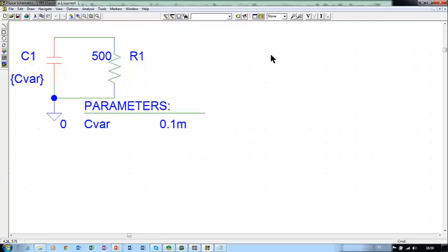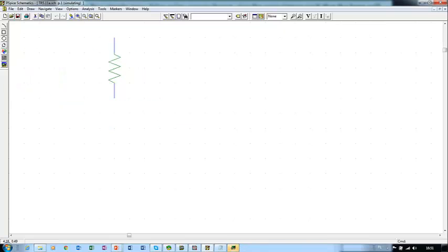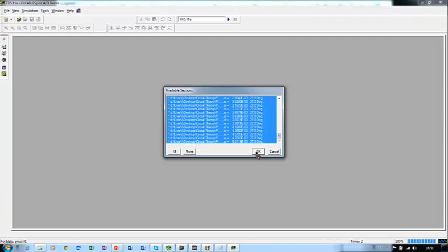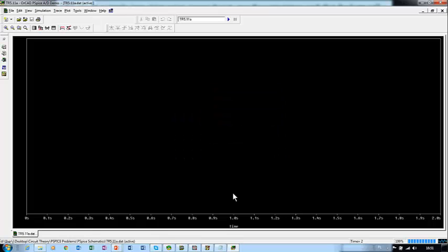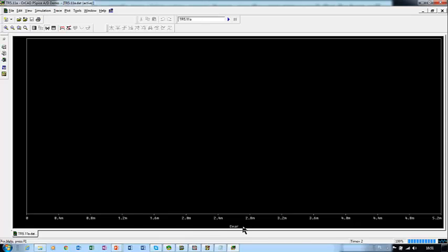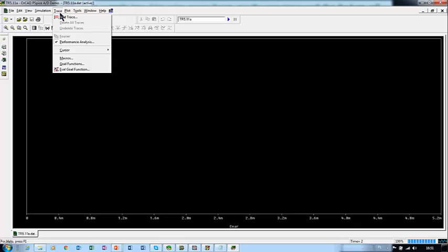Okay, everything has been stored in computer memory already. We may start the simulation. After some time we will finish the simulation. Okay, all capacitances. Now we have a blank window with time on the horizontal axis. We have to click on performance analysis to replace time by variable capacitance, and we have to add trace.